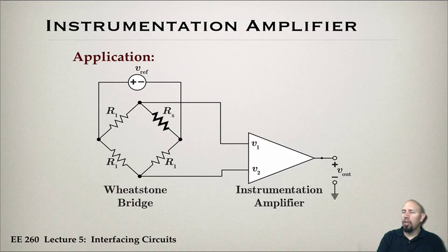So how do we convert a change in resistance value into a meaningful voltage change? A change in resistance, or change in some pressure or strain or light or some quantity, changes the resistance. How do we translate that change in resistance into a meaningful voltage that, for example, the Arduino can read? So this is one configuration for which that will work.